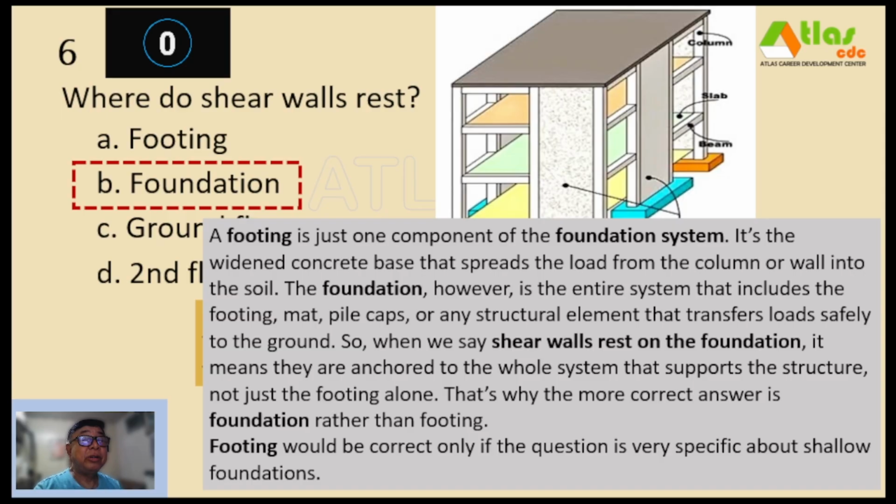The foundation, however, is the entire system that includes the footing, mat, pile caps, or any structural element that transfers loads safely to the ground. So, when we say shear walls rest on the foundation, it means they are anchored to the whole system that supports the structure, not just the footing alone. That's why the more correct answer is foundation rather than footing. Footing would be correct only if the question is very specific about shallow foundations.